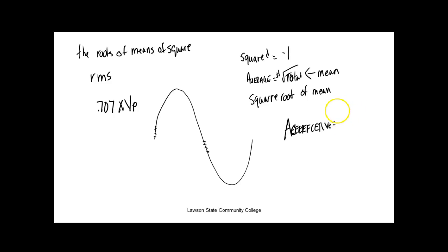It's always, if it's a sine wave, it's always equal to Vp times 0.707. Always. So it would take a computer to calculate RMS. But why do it if it's always equal to Vp times 0.707? So for years and years, when I flip my meter on AC, it just takes Vp and multiplies it by 0.707. And this is a standard meter.